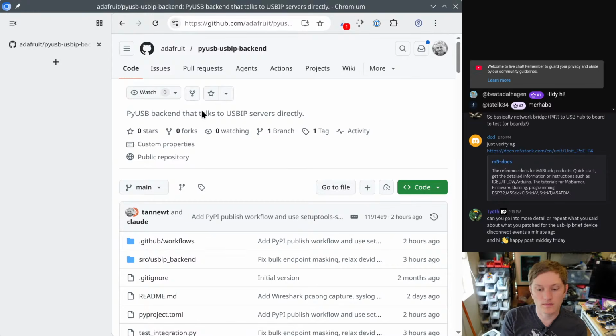But it wasn't handling the case where, if the device left and came back in between those 2 checks of that status, there's this other bit that says, oh, by the way, it changed. And so you can check that too. So even if before and after are say, yeah, there's a device, there's a third thing that says, oh, by the way, the status changed between the 2 times that you read me. So you could know that even though it's both here and here, in between it was gone.